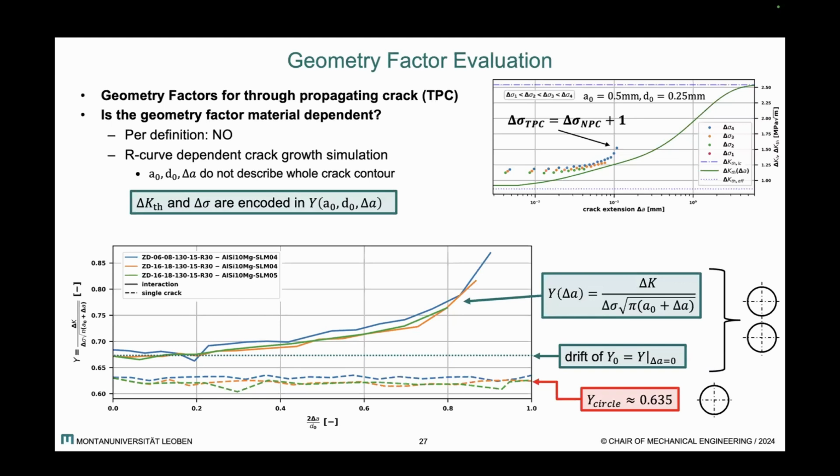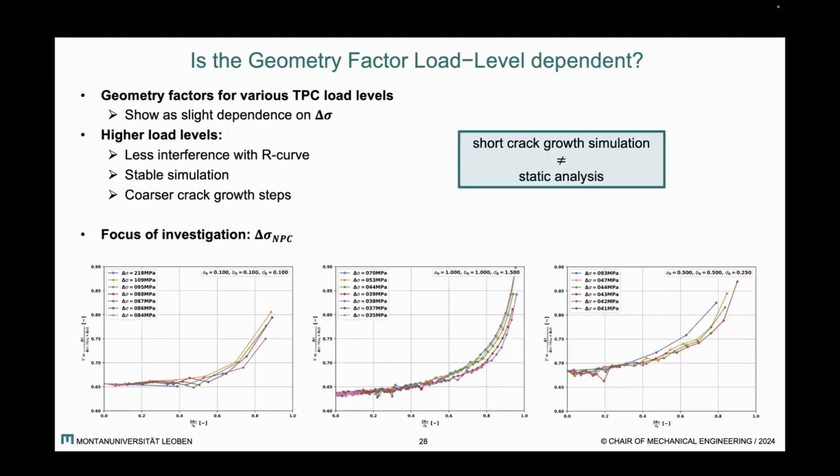Speaking of this load scale dependence, I present to you some results for the identical material and identical geometrical configuration, but with simulations performed at different load scales. So the crack will evolve slightly differently depending on the crack front activation with respect to the R curve. For higher load scales, I get consistently, but slightly, higher geometry factors.